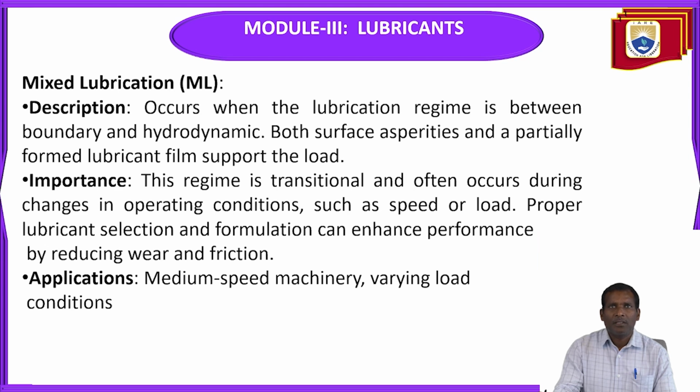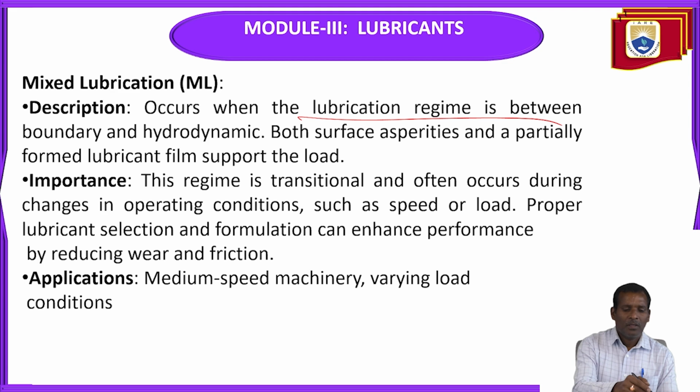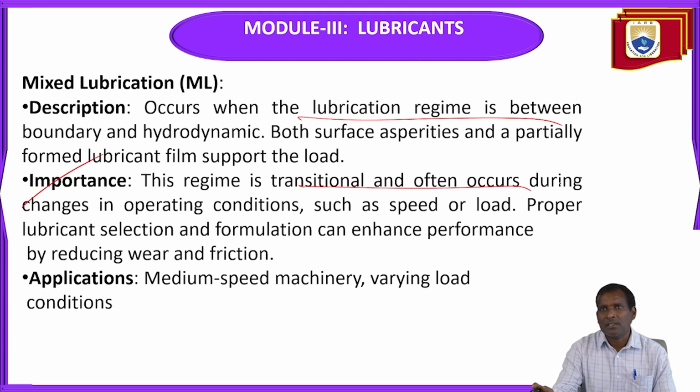Mixed lubrication. This type of lubrication occurs when the lubrication regime is between boundary and hydrodynamic. Both surface asperities and a partially formed lubricant film support the load. The importance is that it is transitional and often occurs during changes in operating conditions, such as speed or load.